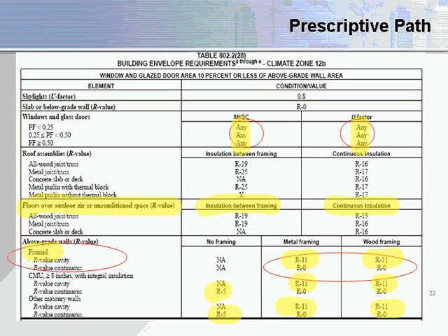Slab edge insulation: the slab between the conditioned space and the vestibule is considered a slab edge. So in this case, we would need to use a slab or below-grade wall insulation requirement, and determine what the R value is going to be for that particular surface. So again, from an IECC prescriptive standpoint, this is how we would go ahead and handle that.